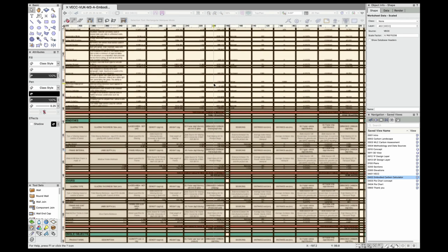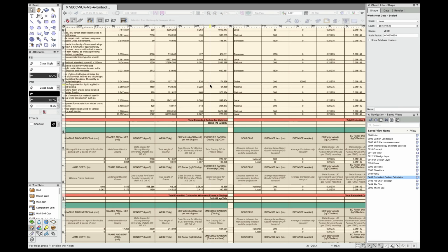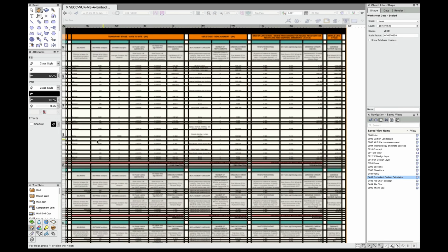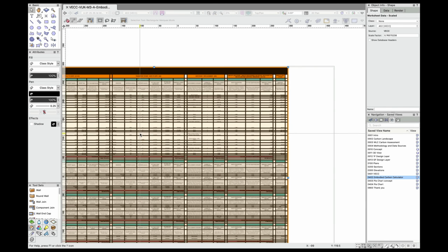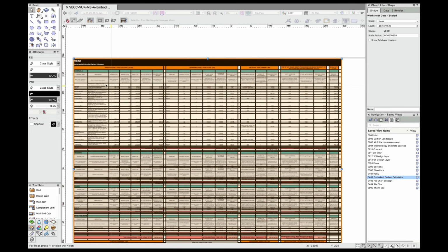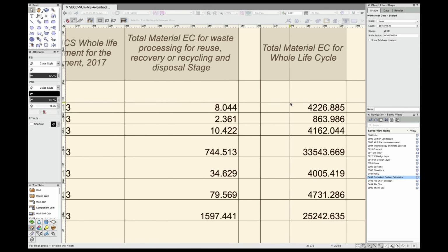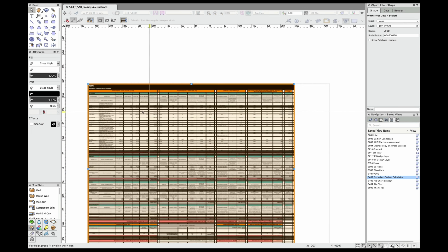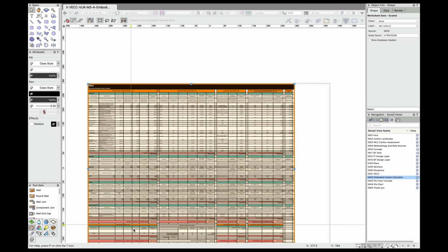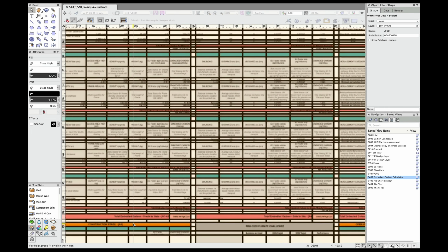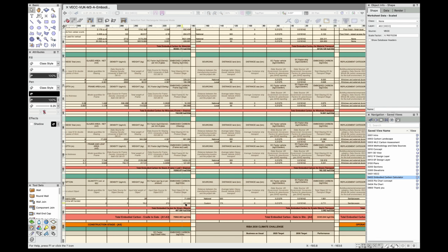So what do all these numbers mean? These are the sort of metrics that can back up your informed design choices, to be able to present these to clients and to have a conversation about which strategy and direction to take in order to reduce the carbon footprint of your design. We can look at the results horizontally for a specific material contribution, or we can look vertically and see how much is product manufacturing contributing compared to transport.